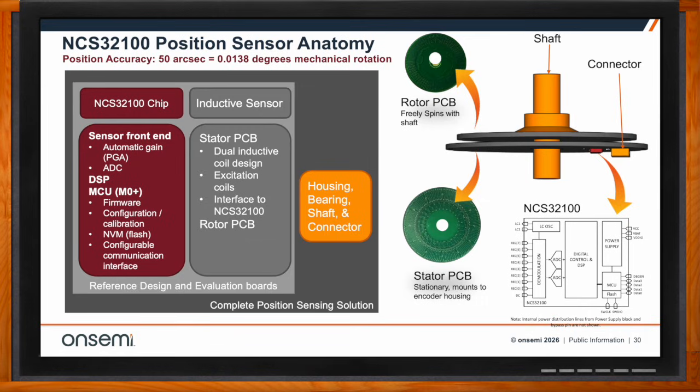And it does that by using these 2 rotor and stator PCBs. The rotor PCB is attached to the shaft of the motor, and the stator PCB is stationary where the product exists. And as that rotor PCB spins, we have a free PCB design tool online where you can design the rotor and stator and the different patterns on there. And with our specialty with this kind of product, we can achieve this really high accuracy. And this is also an absolute sensor as well.